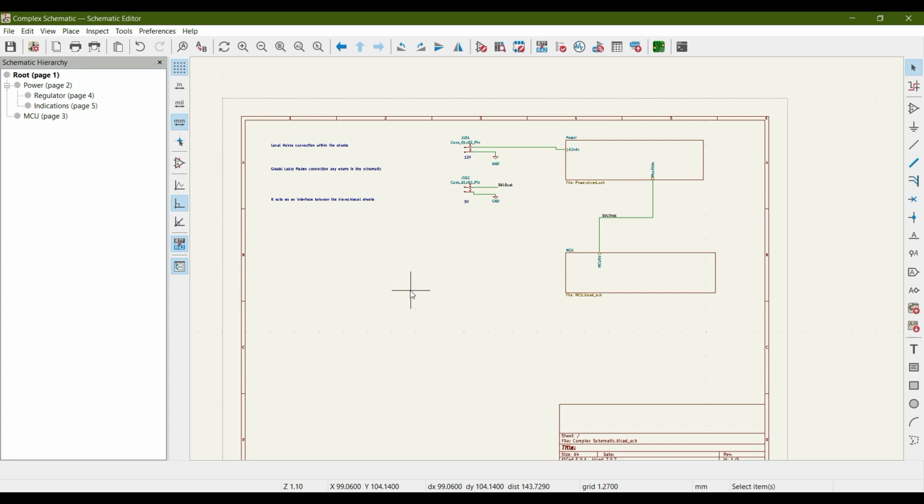If there are sensors in your circuit design, then you can make a sheet where you will wire up all the sensors. However large your schematic is, you can easily draw it using this multi-sheet approach in KiCad.